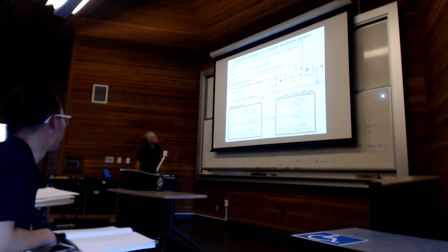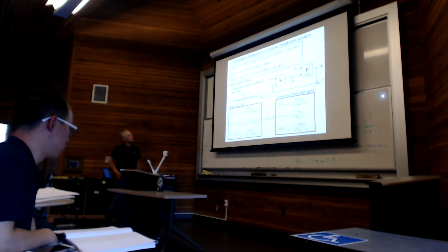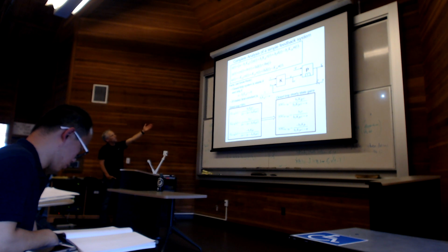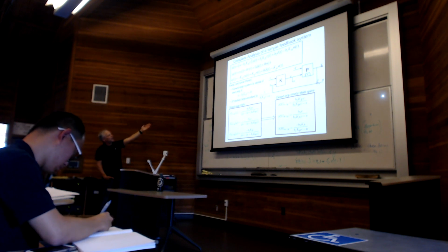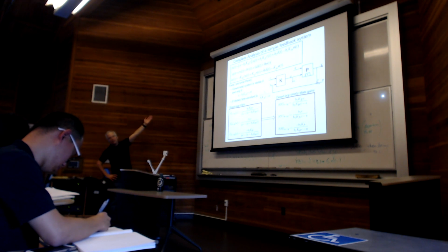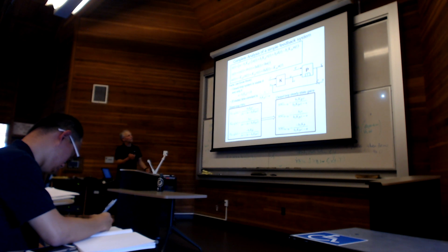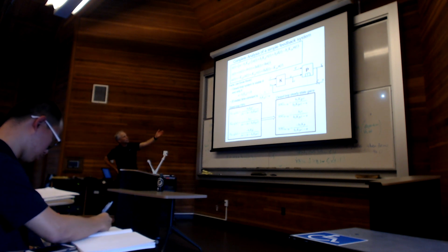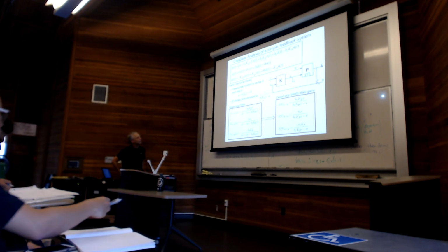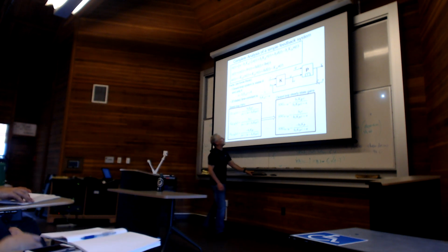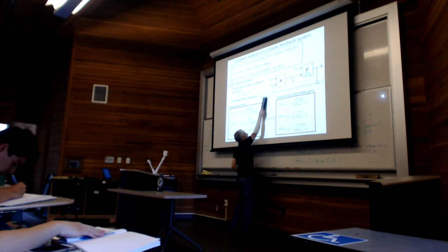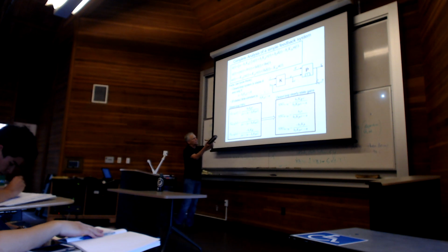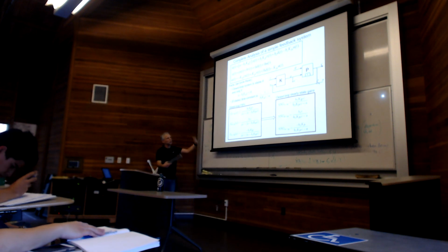So for instance, I guess we already talked about stability. Stability is going to be true if and only if a minus b2 kfbc is less than 0, because that's precisely the closed loop a. So we need to pick kfb to make that negative if it wasn't already negative. And then the time constant is just the negative reciprocal of that. So if I want to make the time constant very small, I probably have to pick kfb very big, and that'll make this fraction become smaller and smaller.